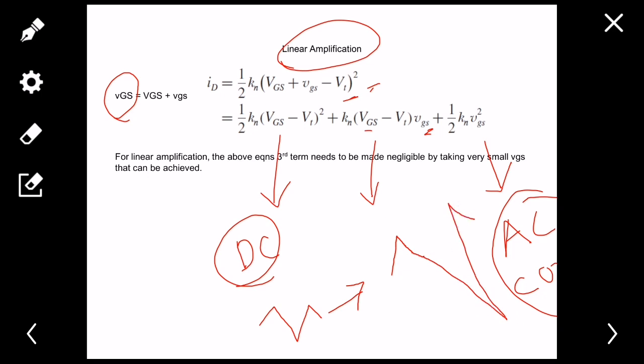So see that maybe your positive portions doesn't get amplified in a greater sense, or amplified by a huge quantity, but your negative portions has been, so it is not actually similar on both the half cycles, right? So this is known as nonlinear, and we don't want this. Okay, we don't want nonlinear amplification. So to avoid nonlinear amplification, we need to avoid nonlinearity.